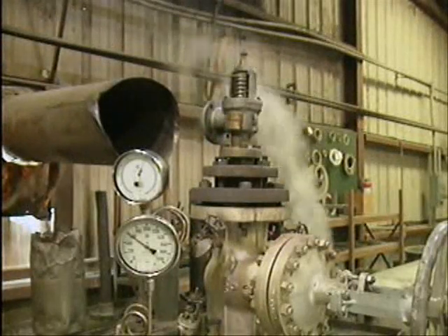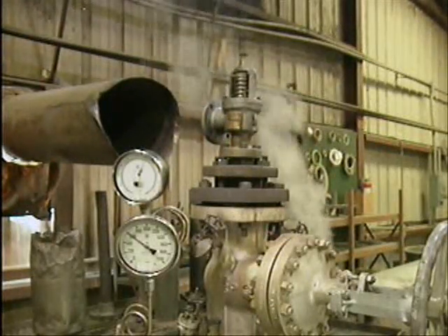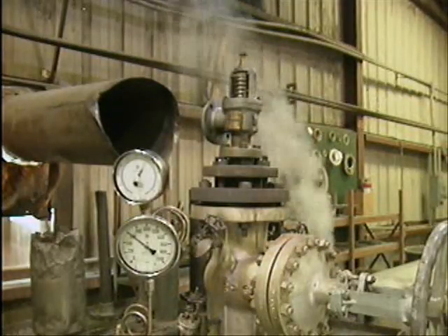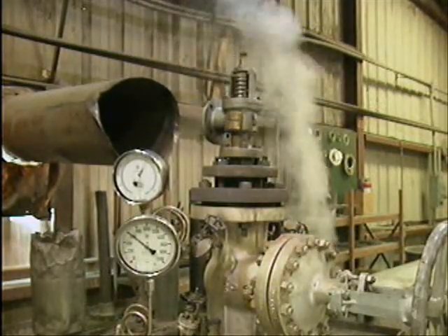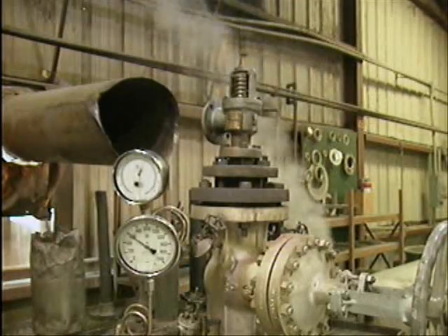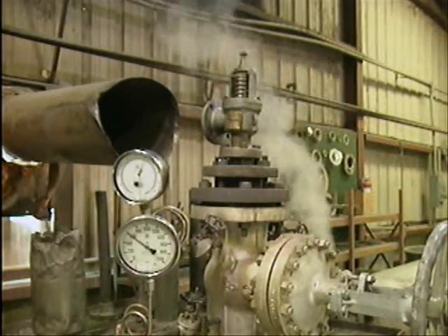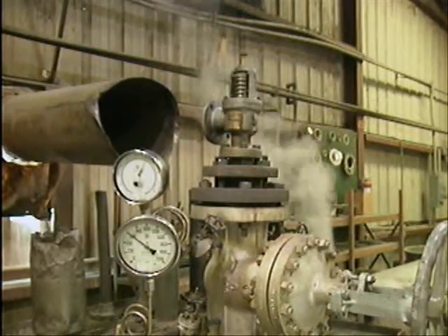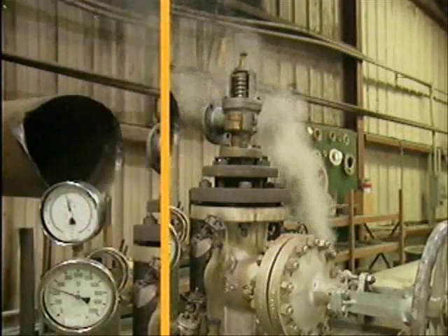Safety valves may also be affected by hydrostatic testing that's done on the system or equipment that the valves protect. A hydrostatic or hydro test is done to determine whether or not the system can tolerate excessively high pressure in case of an emergency. It also helps you detect leaks.